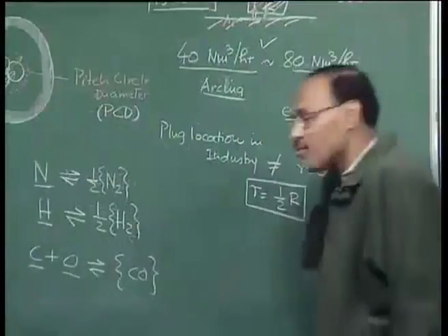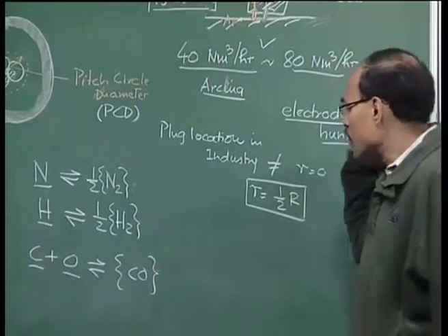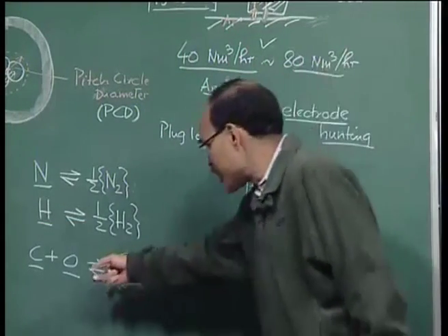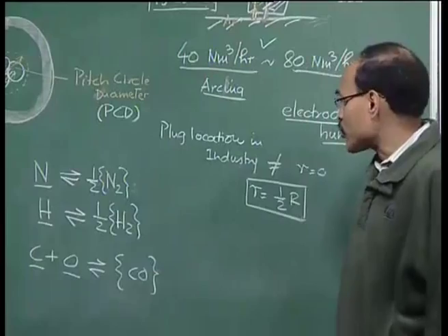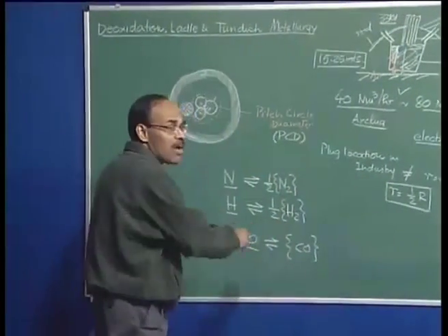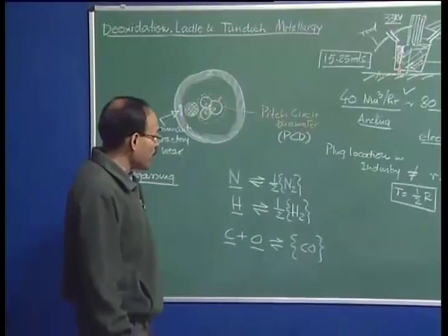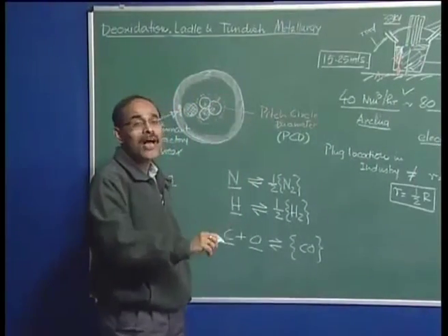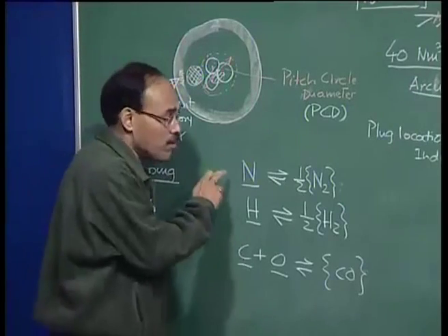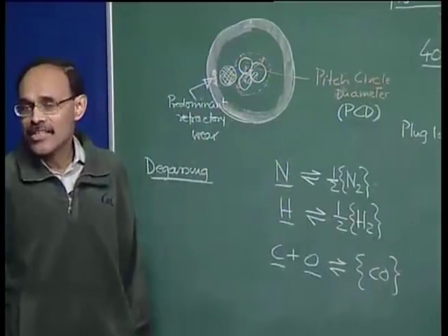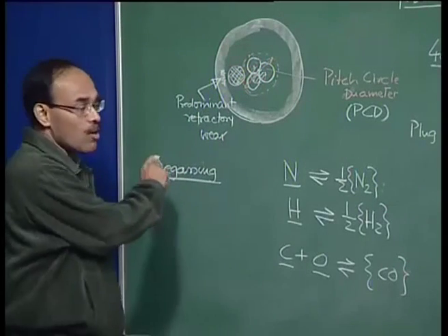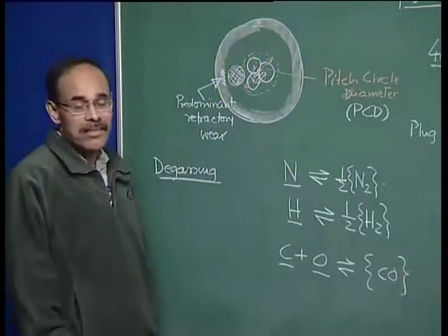By continuously removing hydrogen from the system, we will be able to facilitate the metal to lose hydrogen, and the same is true with carbon monoxide. So, all these gas forming reactions, the 3 reactions I have enumerated here, are going to have a greater tendency to move in the forward direction from left to right under reduced pressure, and that is why we carry out the degassing operation in steel making under reduced pressure.